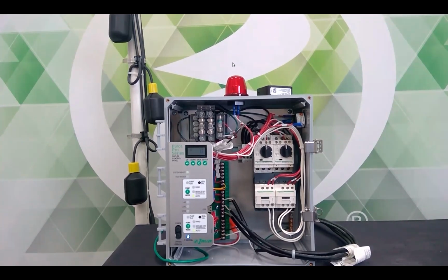By default, it comes as duplex, because I think that's what most people think of, that if you had a lag float come up, you could have 2 pumps running at the same time. But there's plenty of situations where you don't ever want that happening because somebody didn't do the power right, or it's insufficient at the moment, or it's discharging. You don't want 2 pumps discharging to the same place for some reason. There are examples of where you don't want that. You would change that from the default of duplex to alternating.